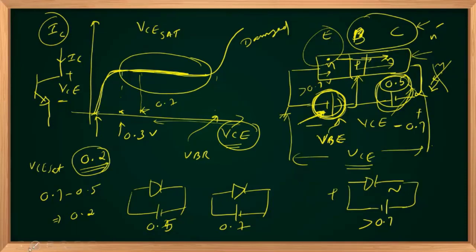So we will say that the transistor is in which mode? Active mode, right? Active mode. In this region, the second junction becomes forward biased. So we'll say that the transistor is in which mode? Saturation. The first junction is anyway always forward biased. Otherwise, no emission of electrons, no currents.